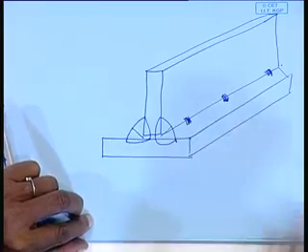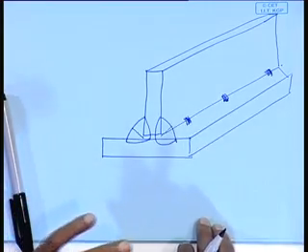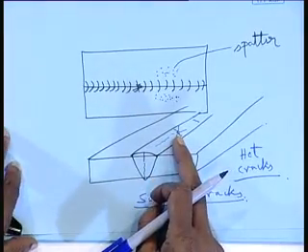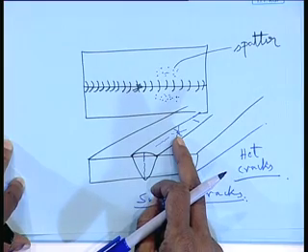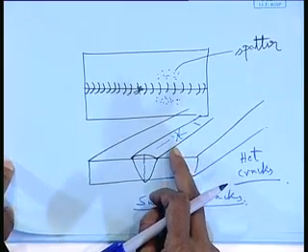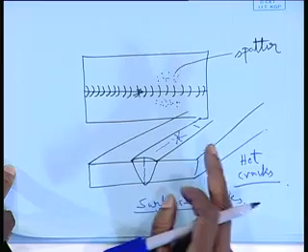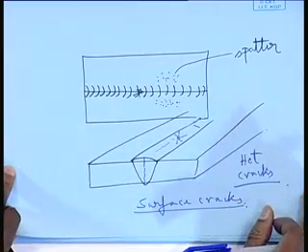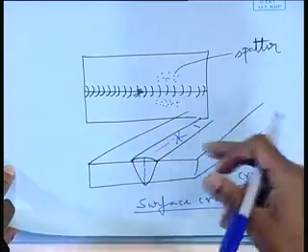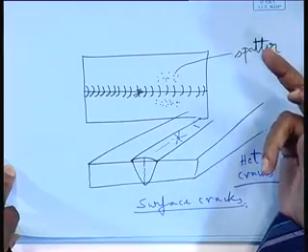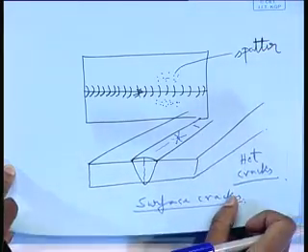So, that is why the surface crack will primarily depend on the welding procedure. It will depend on the restraint on the structure, what kind of stress level is taking place. So, if a defect is observed, it has to be removed and re-welded, but thereby you are not removing the cause of the defect. To remove the cause of the defect, you have to look into the welding procedure, such that in the fresh welding you do, crack or defect should not occur.